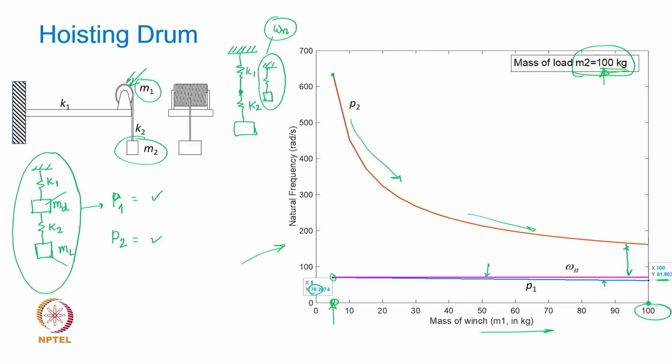So what is the takeaway from this? I mean, what we are inferring is that if there is a large gap or a large difference in the two mass values, at least the lower of the two natural frequencies has absolutely no difference when you compare that value of the first natural frequency with the frequency that you obtain by assuming a single degree of freedom model.